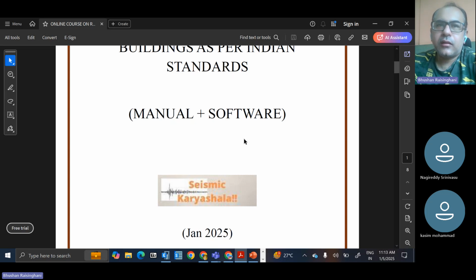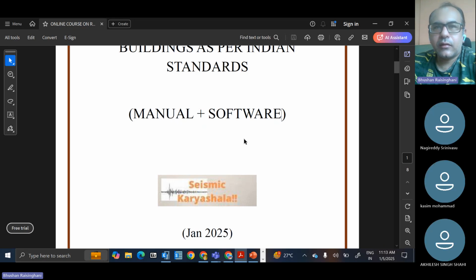So in that case, we take the IS code forces, gust factor method, and design the building with the higher loads. However, if you go through IS 16700, it is saying that if the forces are higher, then we have to go for the wind tunnel testing forces. If they are lower, then we have to take the IS code.